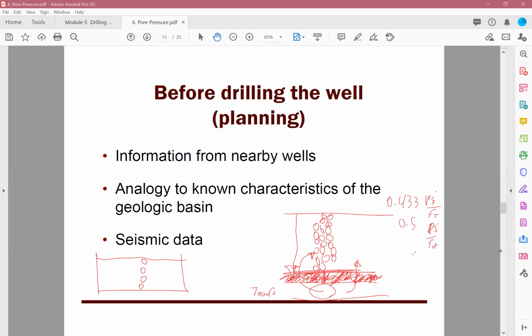Now in drilling, this is very, very important because you do the casing design based on this. You need to design your mud weight based on the abnormal formation pressure, right? So you would need to understand what the pore pressure is, right? And for our purpose here, we design both the mud weight and the casing design. That's one of the goals that we are talking about here, right? Any questions here?